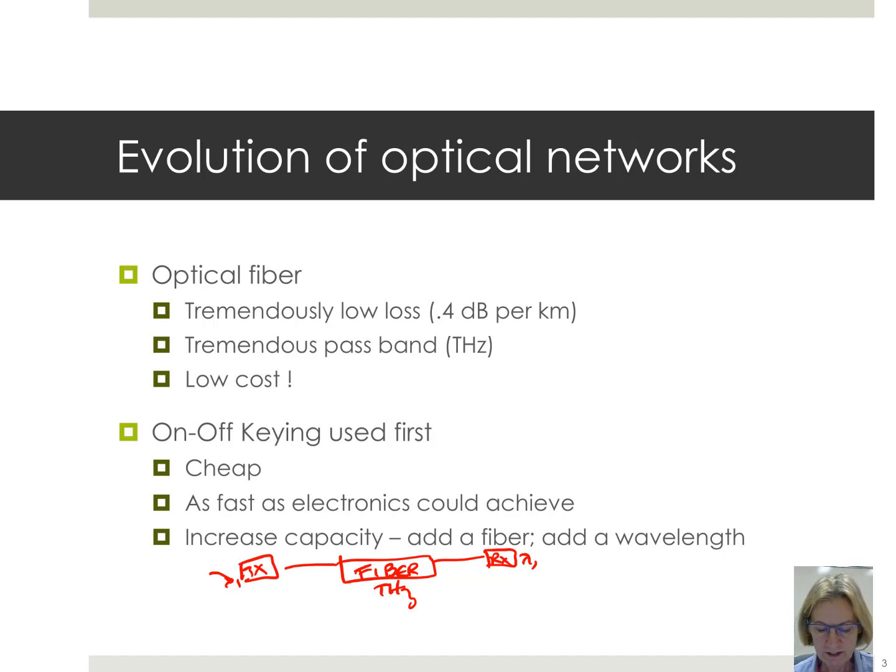And so we would have to have a link that would create a new transceiver for each one of these wavelengths that were exploited as we made longer and longer links. So that meant that we had a lot of capacity in the fiber and we could exploit it. However, the cost per bit was pretty much fixed and we weren't able to get many economies of scale. Every time I wanted to add more data, I had to create a whole new system. Only the cost of the fiber wasn't repeated, but remember, the fiber is low cost. It's the transceivers that are expensive in the end.